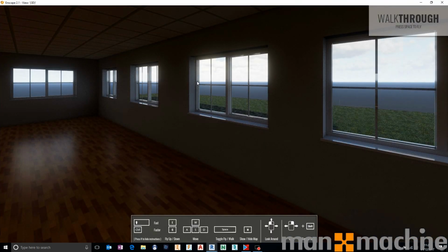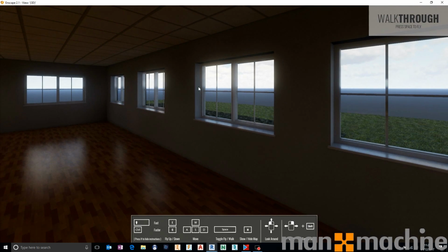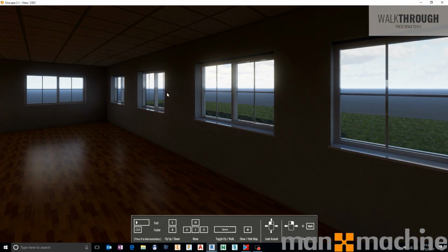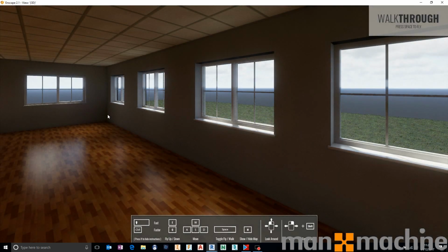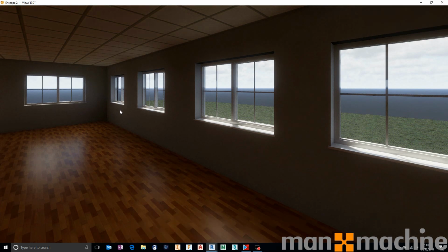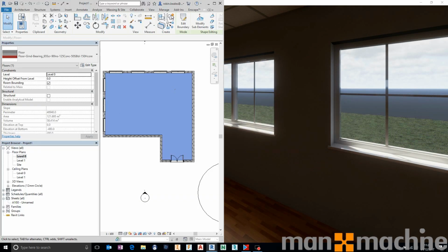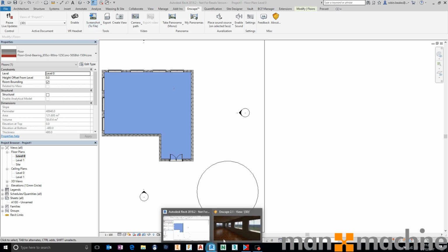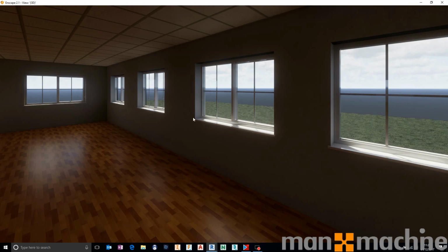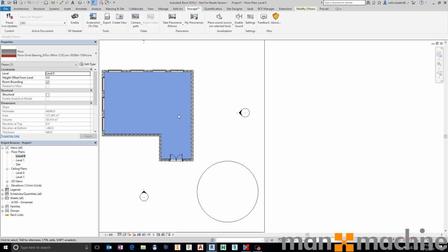So, very, very powerful piece of software. But above that, as well as doing this live and being able to coordinate with our model live and change the time of day, so on and so forth, and whatever it is that you want to do, we can also get outputs, because it's important to note that we can save outputs from Enscape. We can take a screenshot and save it straight to a file. That's really useful if you're happy with the quality that Enscape's giving you on the screen at a given point in time. It's the same as saving a ray traced output if you like.